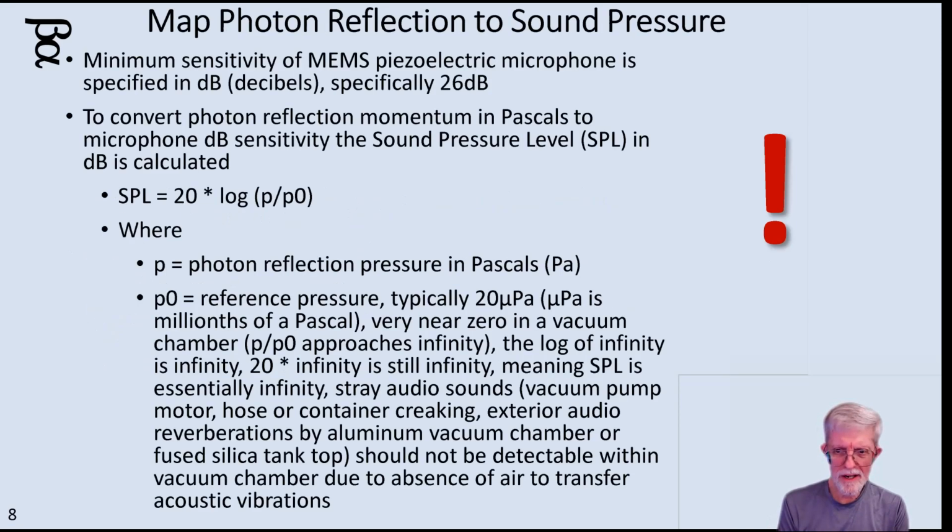And sound pressure. I had to evaluate the technology of this microphone as to when air under pressure, air vibrations of sound, hits this little piece of piezoelectric material, what is the pressure, what is the force against that to do the piezoelectric effect to produce the voltage? What is the pressure of sound waves? So I had to evaluate what is the minimum sound pressure that this thing can detect.